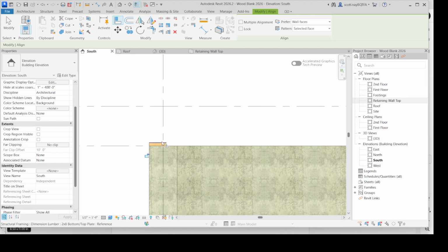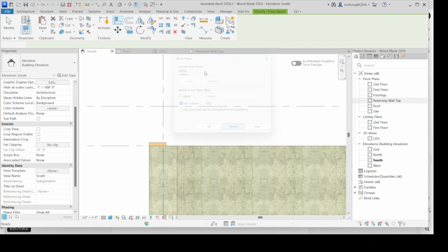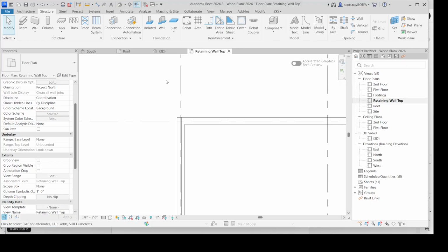We are going to have a web joist going this way that are a funky dimension. So we're going to have to kind of create a custom rim joist that'll cover that and be the same height. So if we come into our beam, again, go to structure, beam. Okay, let me go to a plan that'll work. There we go.